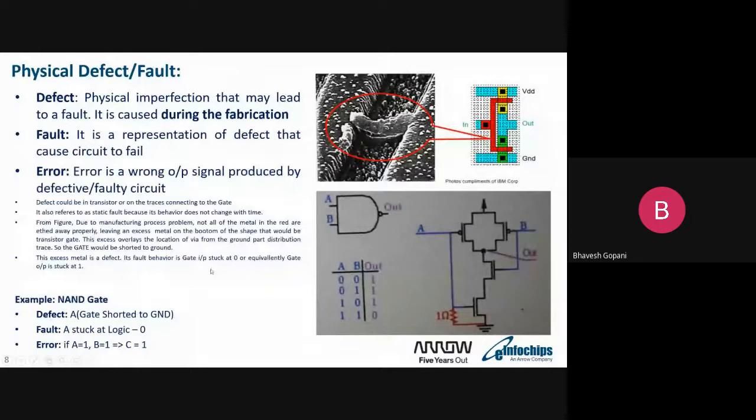So initially when we are generating the vectors, we need to target certain faults like stuck-at fault, transition fault, path delay faults, IDDQ faults, cell aware. There are n number of different bridging faults we need to target. So patterns or vectors are generated accordingly only. So we know which faults we are targeting during DFT insertion, and based on that we deliver to the silicon ATE, and if something fails, we get the errors, and based on the errors again we need to identify what the defect is.